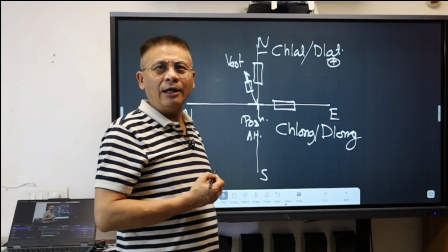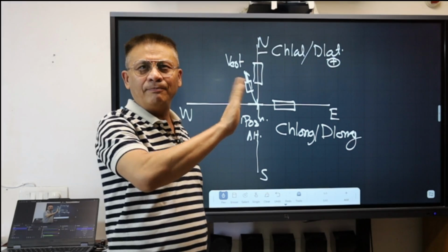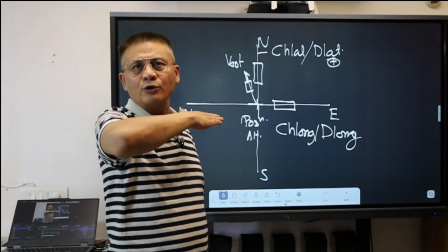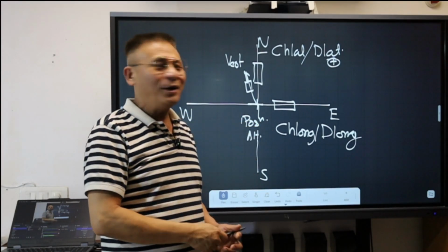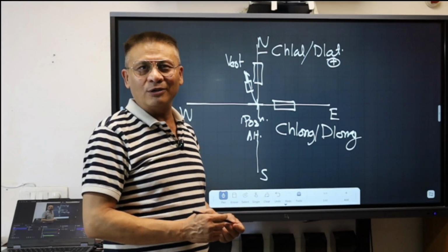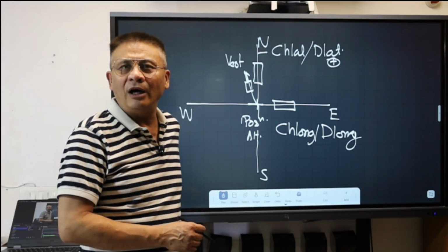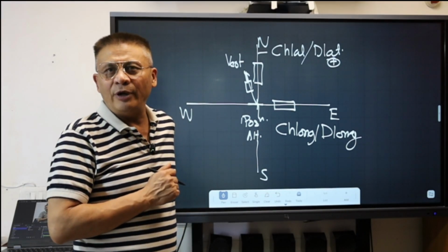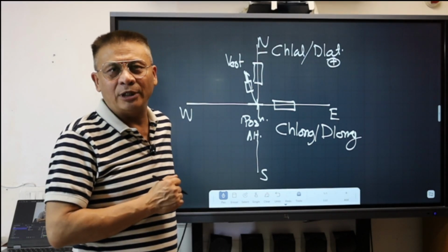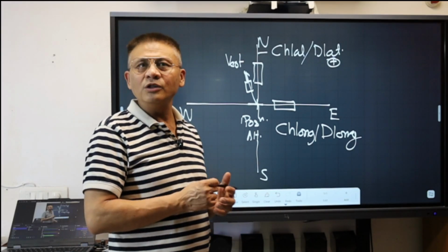But as we know, the aircraft always maneuvers. It pitches up, down, it rolls, banks, and it also yaws. Therefore, these accelerometers, which were initially aligned along the east-west direction, the north-south direction, or the vertical axis, will be displaced from the direction in which I need them to be aligned. So these accelerometers need to be placed on a platform which is gyro stabilized.